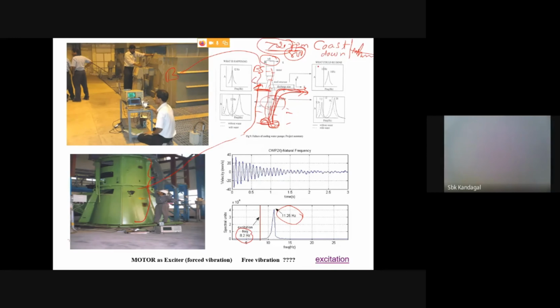So this is how the electrodynamic shaker principle works. That is one part of it. The second part is that one can use the existing hooks and the crane girders to assemble something you can use as a pendulum, just to hit the structure and try to find out its response, to find out the natural frequency of the system.